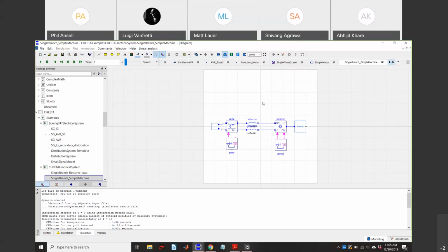So you have to convert the DC power into AC power because the motor is usually going to be an AC motor. Right. Okay. So the inverter on this side, the PWM is going to be used to go from DC to AC. And it will also need some control functions. That PWM block is very simple. And finally, we don't have it here because we have a very simple model of the motor. But if we have a correct model of the motor, that motor will also need a variable speed drive controller that does a similar function to the PWM.